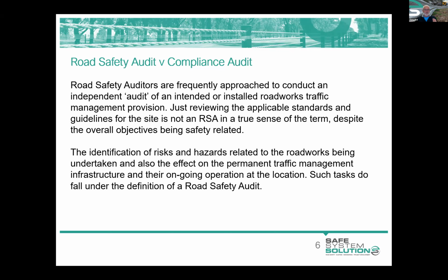So, yeah, detours, there's certain risks with those. Is the detour route capable of taking the traffic loads or the traffic volumes of the road we're managing? So it's all of those questions to be asked, and it might be a combination. And the engineering side of things is part of it. Can we put up some type of isolation? Can we put in some speed management? Can we get delineation, some chicanes or the like, just to slow that traffic down? So it's those types of outcomes we want, to try and reduce those hazards.